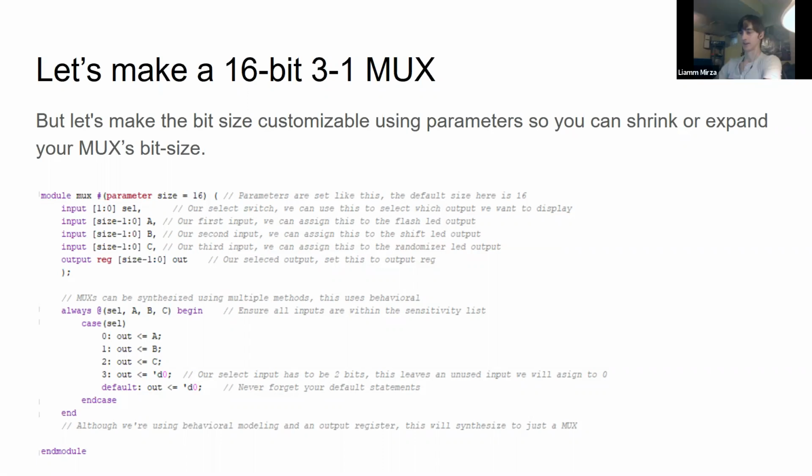Because if you didn't have that, then you get into the case where the behavior for your FPGA is unknown, so you can't guarantee what it will do. When that happens, Vivado will do one of 2 things. It'll silently delete 90% of your design because of it, or it'll give you 100 errors.